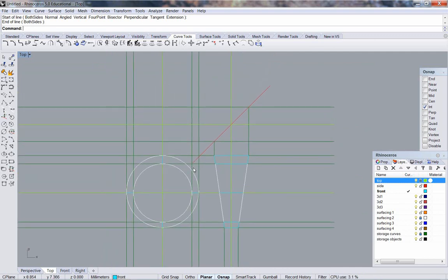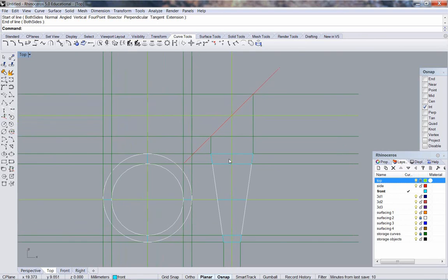So now, in the top view, I'm going to bring my cross sections for those 4 main cross sections up and around. Okay. Well, for the top, I'm going to have to give these center ones here, I'm going to use dots, points, to plot them, because they're all in a straight line. I have 2 cross sections with plenty of information all lined up along the center line. So I'm going to use points to demarcate where they actually land.